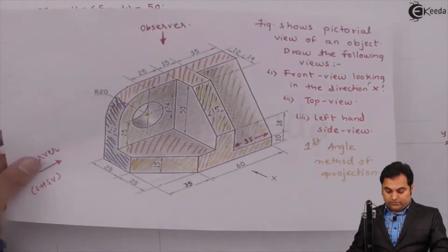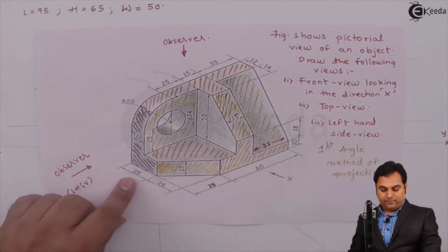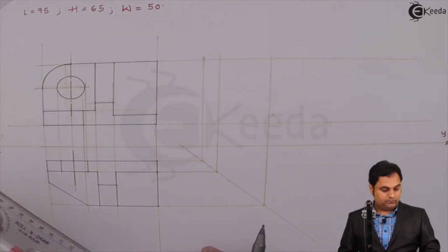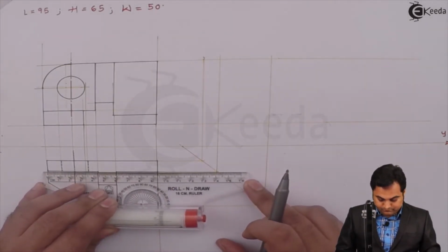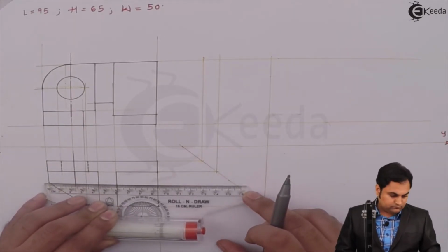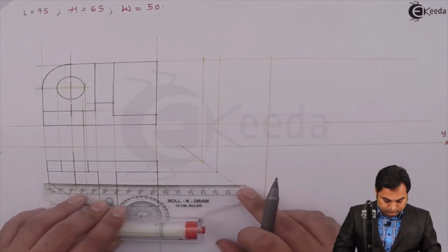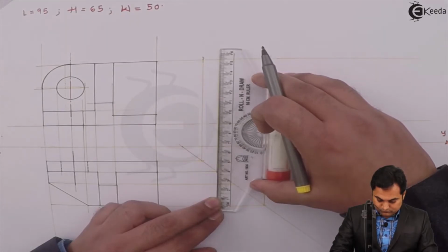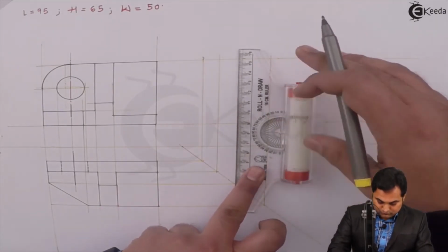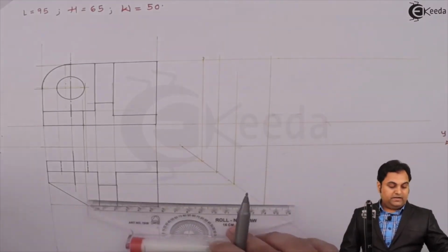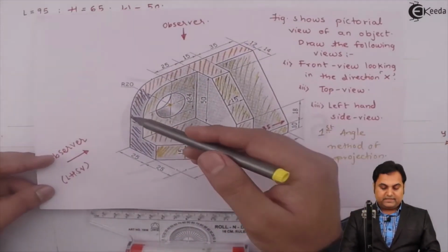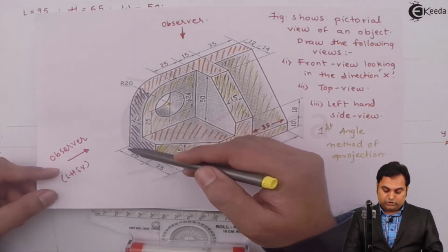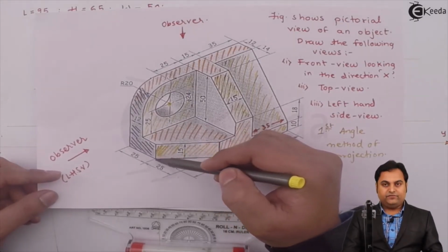Then here this portion is having a width of 25 mm. So that 25, I can take it from the top view. And here the height of this portion, as I can see, 12 mm was the width. Next of the vertical portion. For this horizontal portion, width is 25, but height is 15 mm.